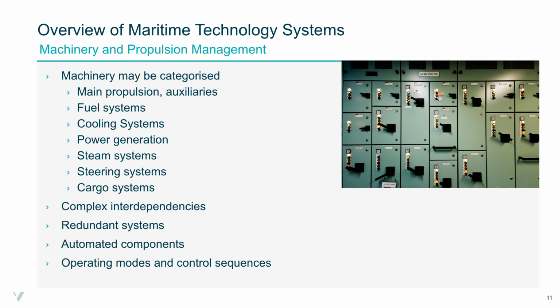So the fuel system will provide fuel to the engines to consume, and the fuel will have to meet a certain specification. And we'll have an OT system that will be monitoring it. It'll have the ability to measure the viscosity, the temperature of that fuel as it's delivered, and provide a control input as that fuel varies. The controller will have the ability to increase the heating or whatever might be required, or decrease the heating to maintain that fuel within specification.